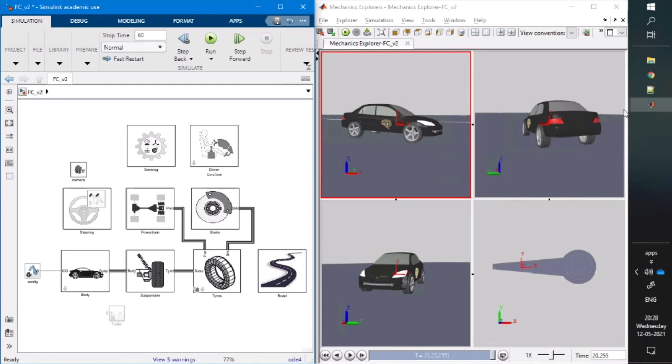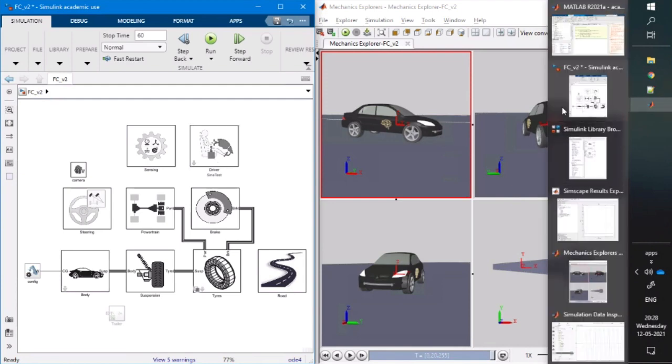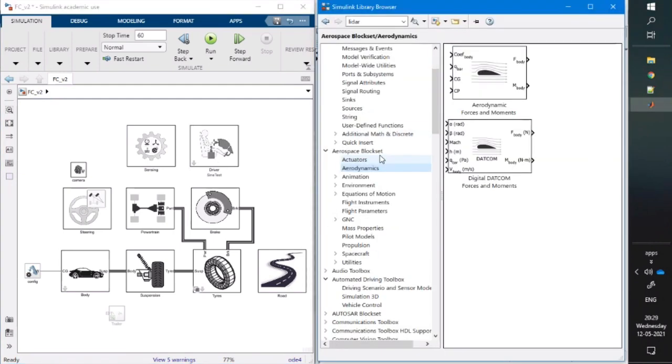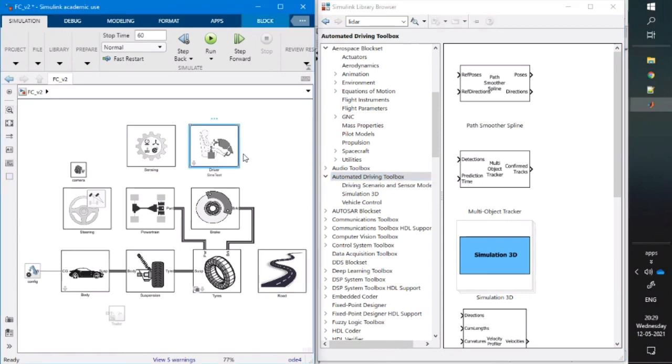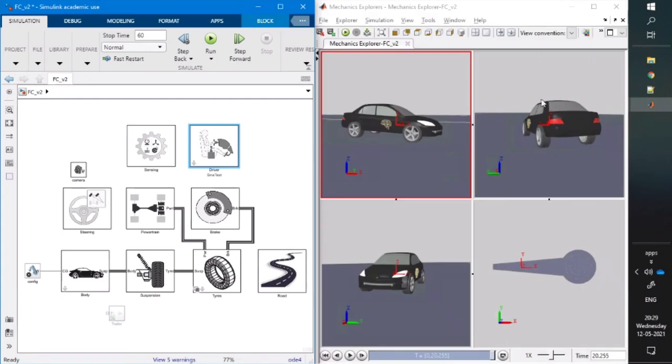You can do more stuff. It is not just the inputs that you can give. You can also generate waypoints using Automated Driving Toolbox. There's an app where you can build intuitively. If you want the more programmatic side, it's also based upon object-oriented programming. So you can build multiple variations with a small piece of code, integrate all of them together, and have your driver drive all the way along. You may not go physically because of COVID situations, but you can drive virtually wherever you want. You can import map files and build a road accordingly.